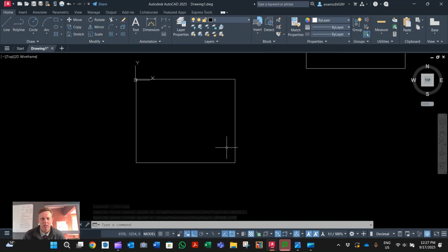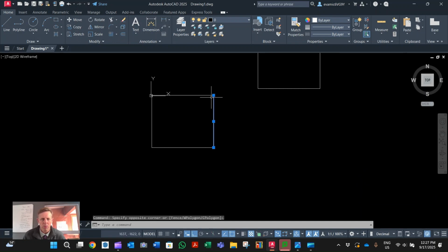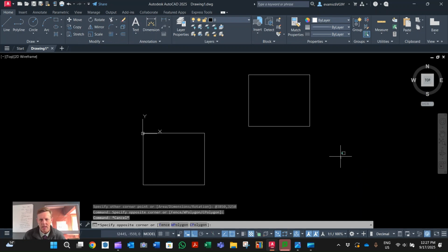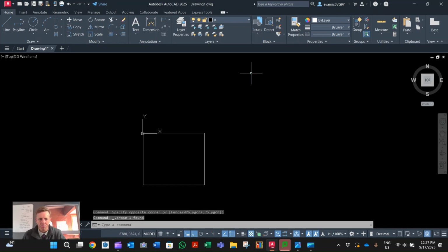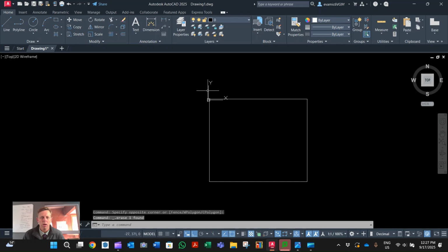The reason we want it like this is because we're going to move and offset some of these walls, whereas this now is one fixed block. What you would have to do then is explode this, okay? I'm not going to do that now. We're probably going to explode a block later, okay? So I'm just going to move my cursor over a little bit because it's in my way.